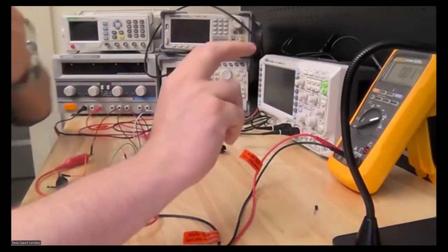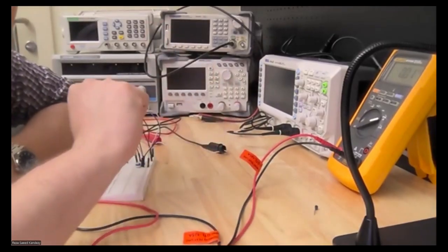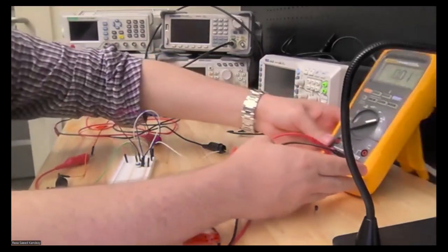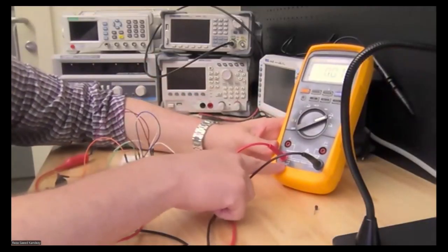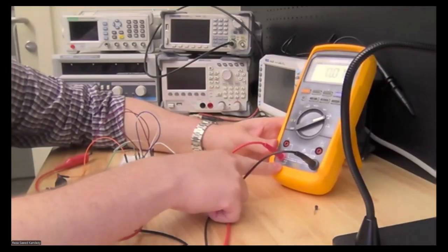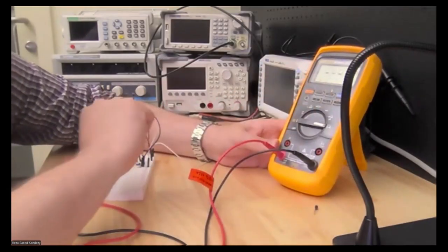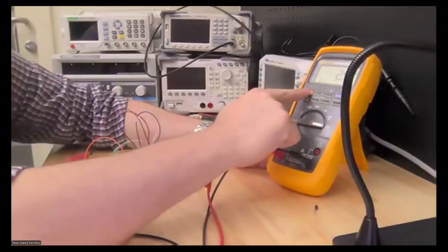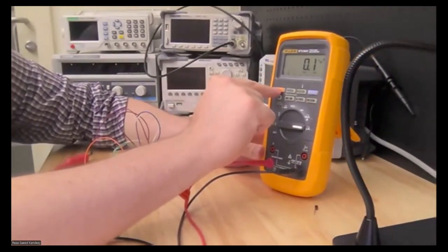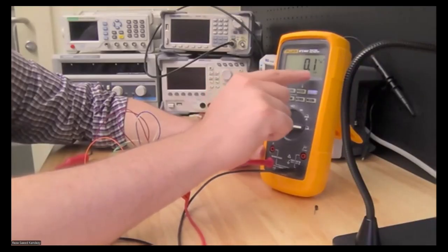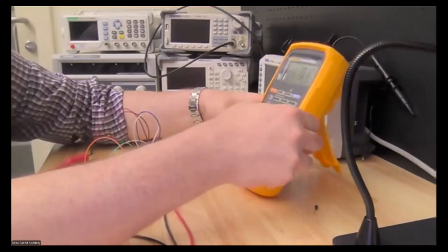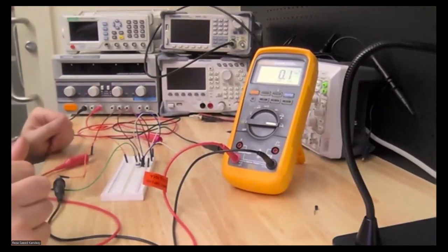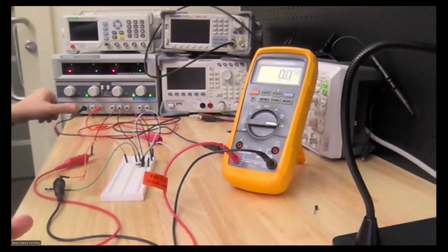Now, as I mentioned in the assignment, we expected around 50 microamp. So we are going to connect the probe to the socket that is good for microamp measurement, and we are going to set our multimeter to the microamp. Again, be careful. The default is AC, so you need to change it by pushing the orange button. Change it to the DC. Is this readable? Yeah. Now that we are okay, I am going to apply my voltage.